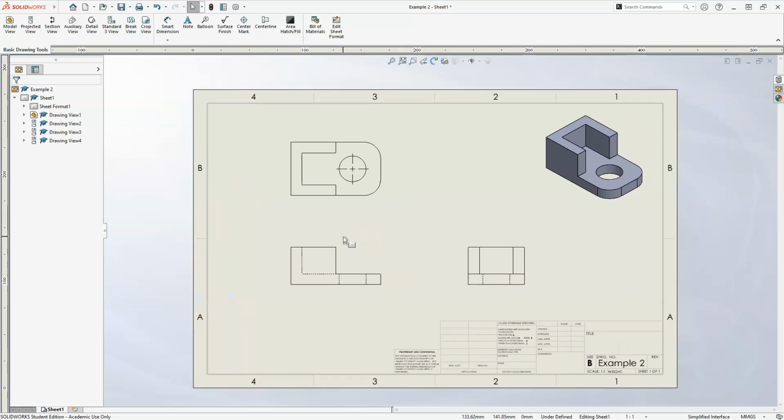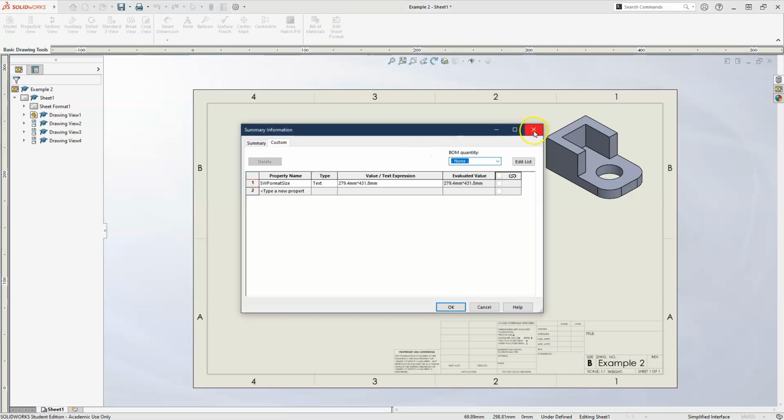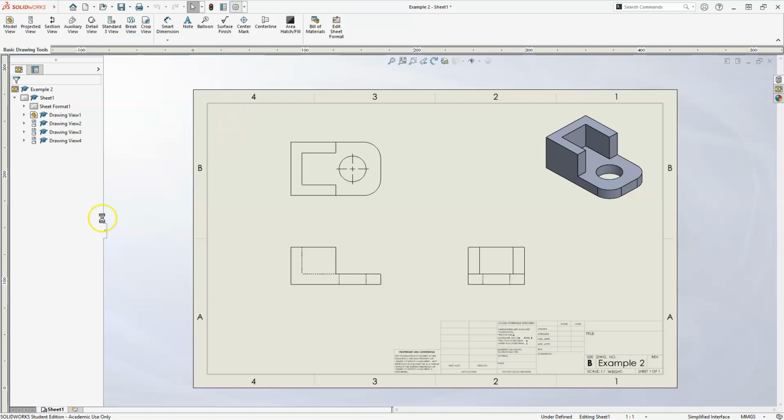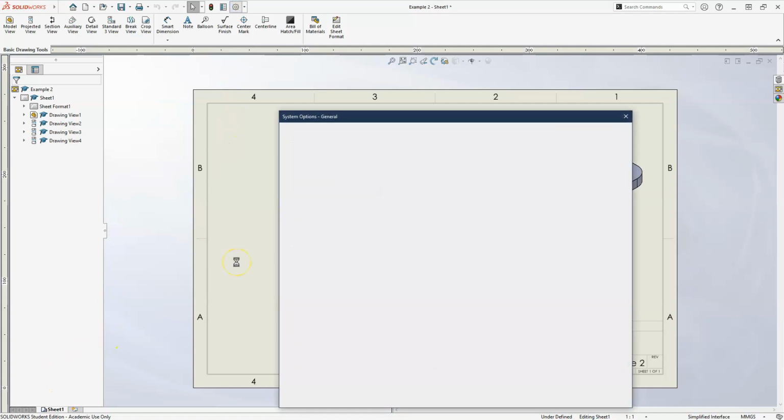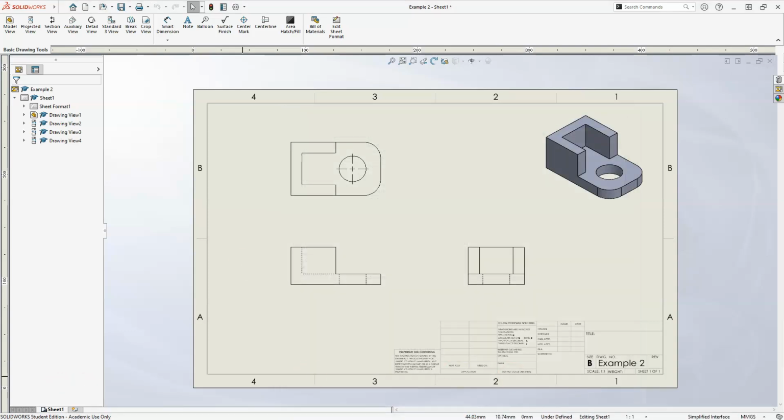Another thing is that we are using the scale based off of the drawing here. So I can leave this drawing set to 1:1, or I can go change that up here in the file properties, right? Oh, nope, the wrong one, in the settings. Once this dialog box appears, you'll see that we do have a scale and things of that nature set up in here. Another thing while I'm in here is that I will show you how to adjust the dimensions and things of that nature, okay? So let's kind of go back for a second here.